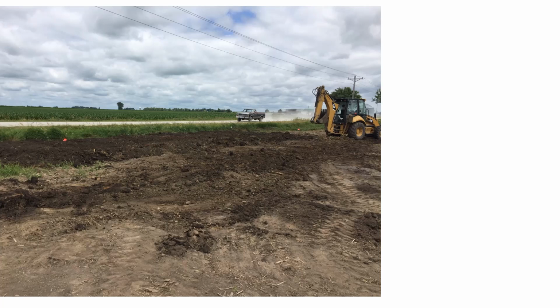In Illinois, it's pretty common to just have an open pit bioreactor where you bring wood chips all the way to the top and you just dispose of the soil back into the field. In Iowa, most of the time we're seeing the soil cap being utilized. Here you can see the soil is put back over top of that geotextile fabric. Then it gets reseeded. If it's in a CRP, you follow the CRP seeding plan. Otherwise, you can just put any grass out there.